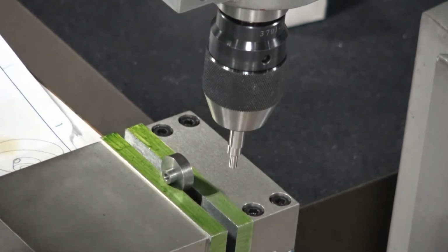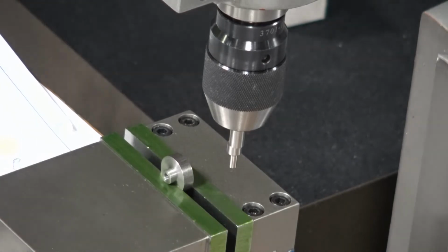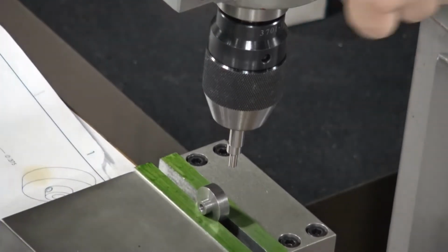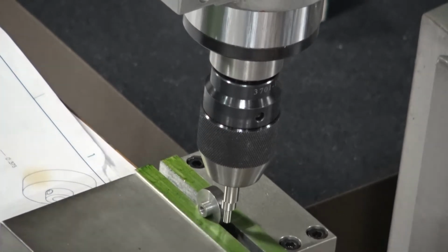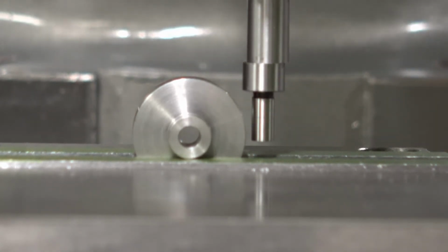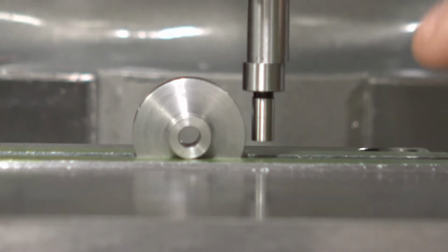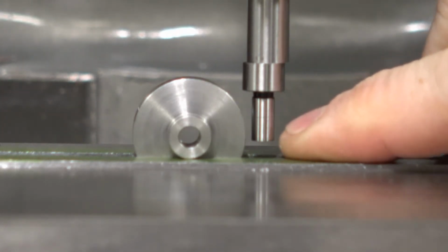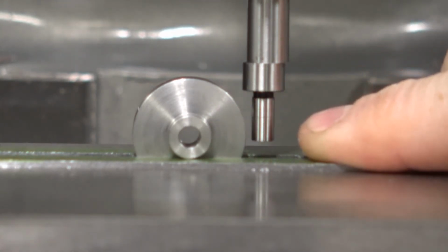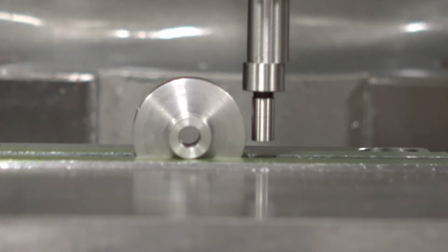Go ahead and shut that off just so that it's a little quieter in here. So now I'm going to position that edge finder close to the outside diameter of that 1-inch cylinder that the flywheel's made from. So we're going to bring our edge finder down, and we want to make sure that the tip of that 200 thousandths diameter is at least at the equator of the circle. We want it to be at the equator or a touch lower.